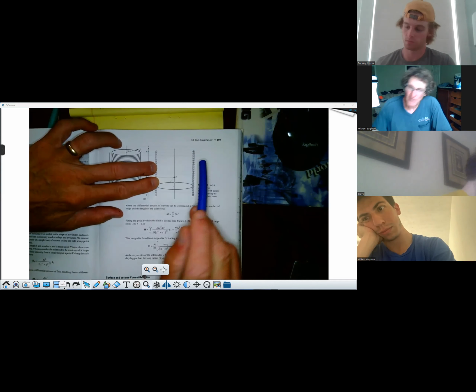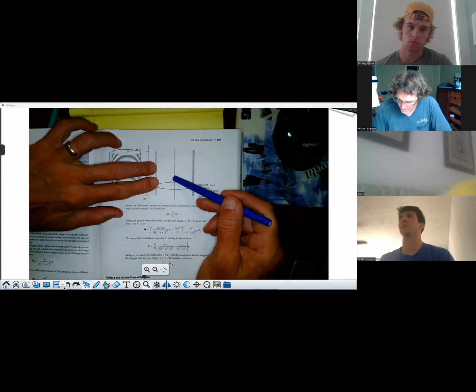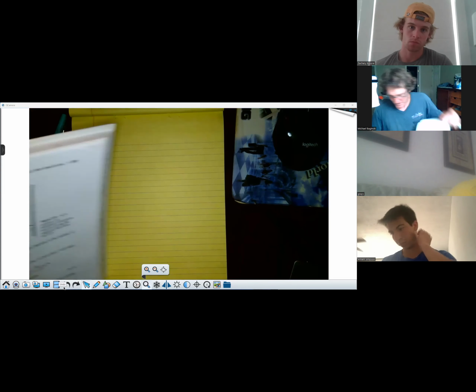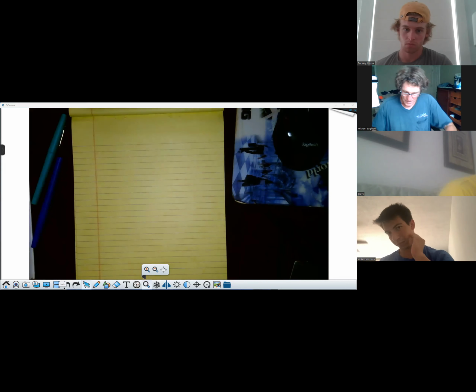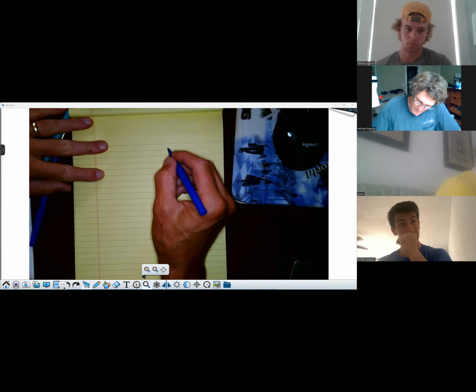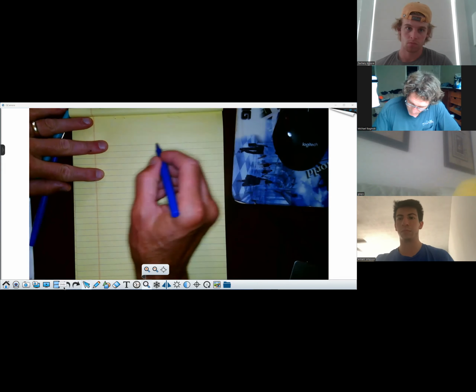We found the actual H field, but it could be a differential H field from that. If you have a whole lot of turns of wire, and we just look at a couple of turns with a thickness dz, suppose I do this. I'm going to say I got a loop of wire here.